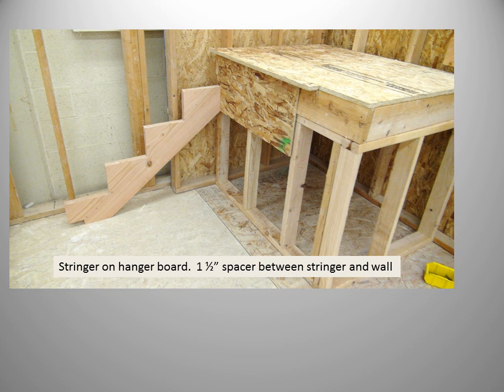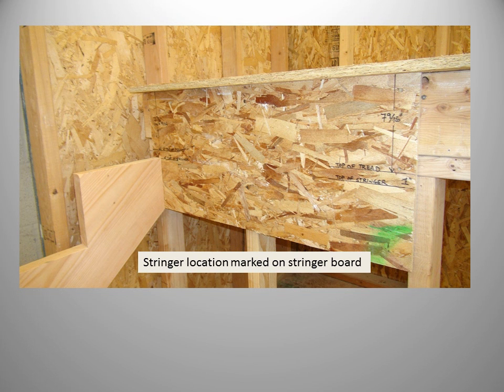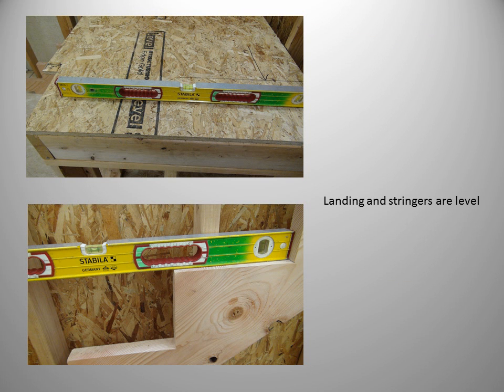Remember to install the 1.5 inch spacer board on the inside of any stringer that is flanked by a wall. This is our space for drywall and the skirt board. Refer to the flooring material concepts lesson for how to locate the top of your stringer. Be sure to double check your stringers to ensure that they are level.